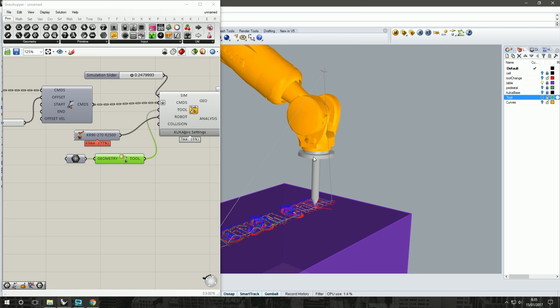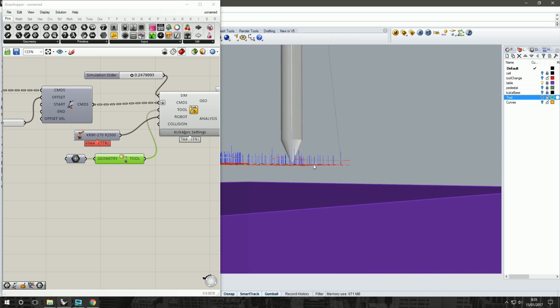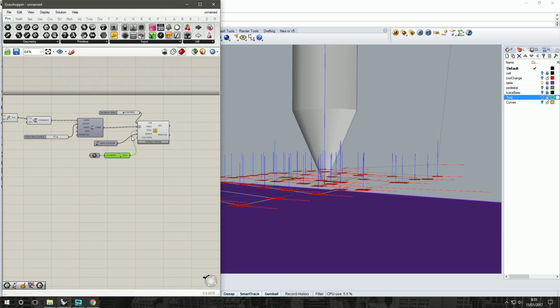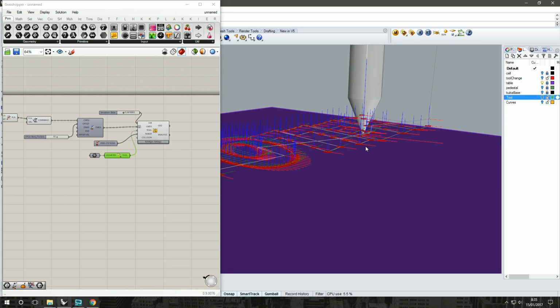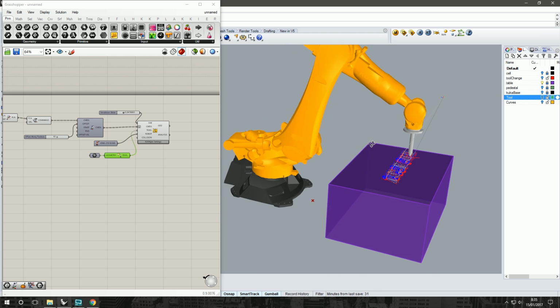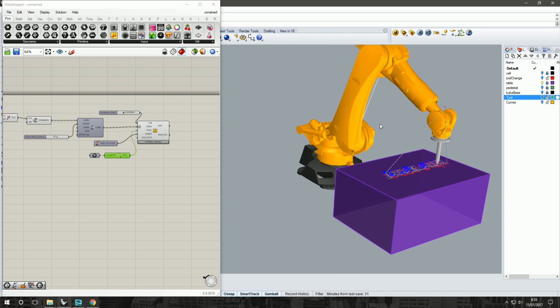So now the robot knows what tool is on. It's 320 long and it's rotated down so that it's going down in the Z direction. So the tool now lines up with all of these planes. And that is the simple way, what I'd call the simple or basic way of drawing or setting up an engraving. You could have a tool bit on a spindle,